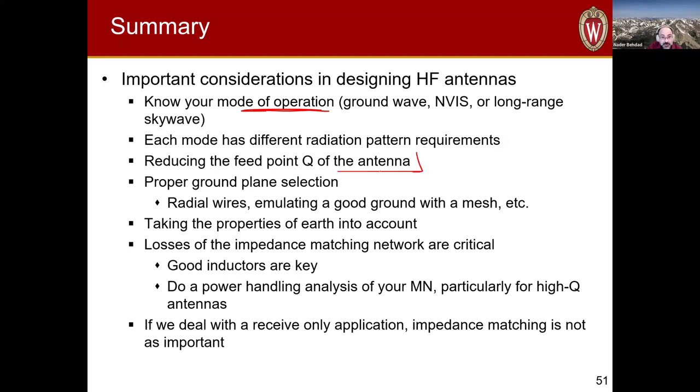One thing that we saw, which was very important, is you need to reduce the feed point quality factor of your antenna by any means possible, right? Because that will significantly simplify the subsequent stages of the design of your RF systems and impedance matching network. To the extent that you have control over your ground, proper ground plane selection is important. You can use more radial wires or emulate a good ground, which would have a really important payoff.